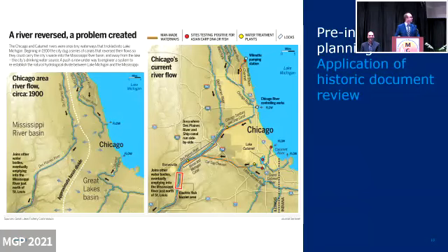But in any case, what this caused for us in the investigation at these sites along the Chicago River is that for a portion of the operations, the water body was flowing to the east, and then the latter portion of their operations was flowing to the west. And so we needed to be mindful of the change in the hydraulic conditions as that affected how NAPL was migrating in the sediment over the course of the MGP, and design our investigation strategy accordingly.